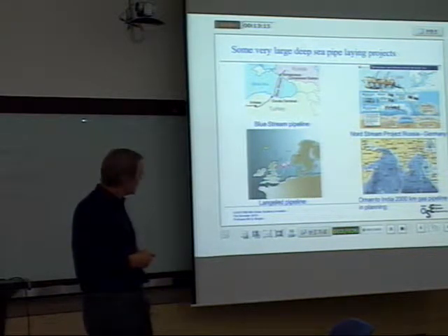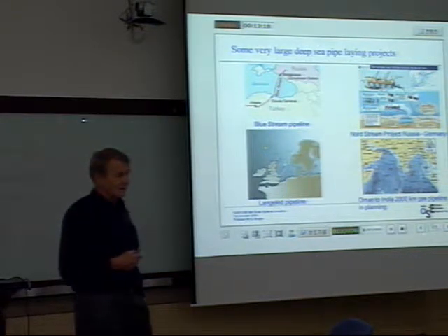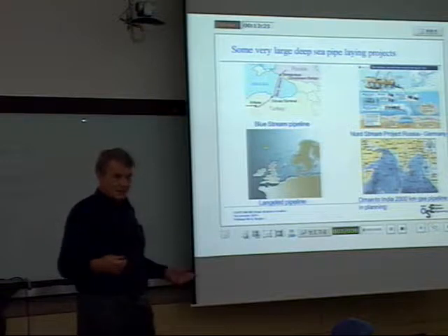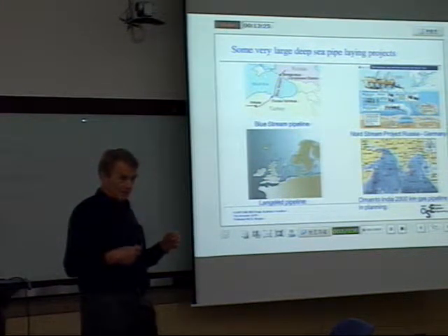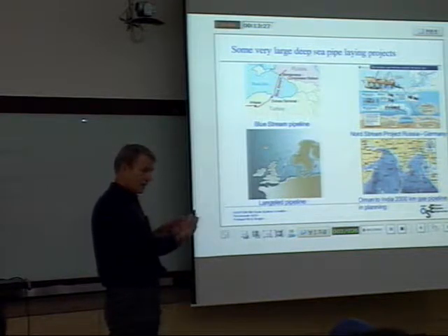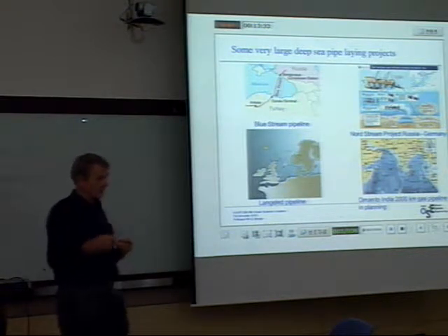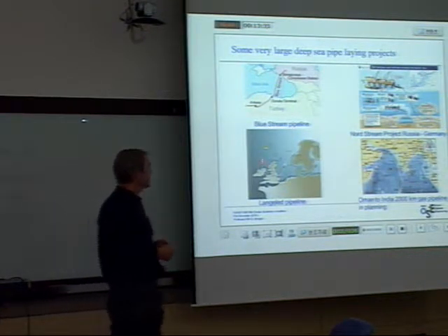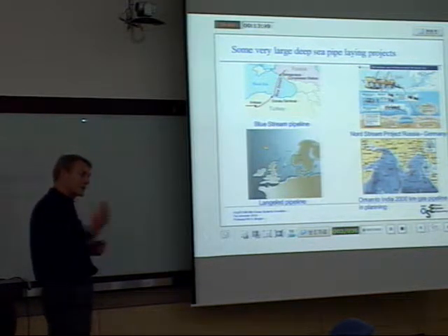But I think here in the middle there's a so-called booster, and the booster is then increasing the pressure in the pipeline, because you have friction, of course. Even if it's a gas, there is friction and lowering of pressure. So you need to boost up the pressure to have sufficient speed of the gas going through the pipeline.